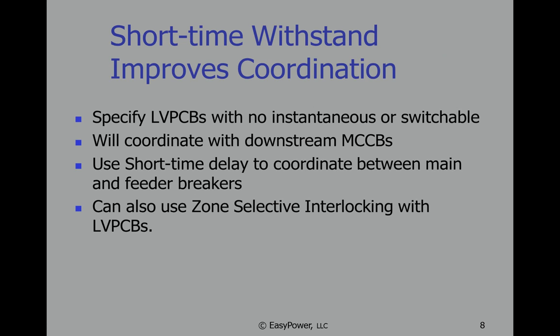So as we've said, the short time withstand that you get with the low voltage power circuit breakers does improve coordination. But again, you need to buy the trip unit without instantaneous or specify one that's switchable on or off. And these will coordinate with your downstream molded case circuit breakers.